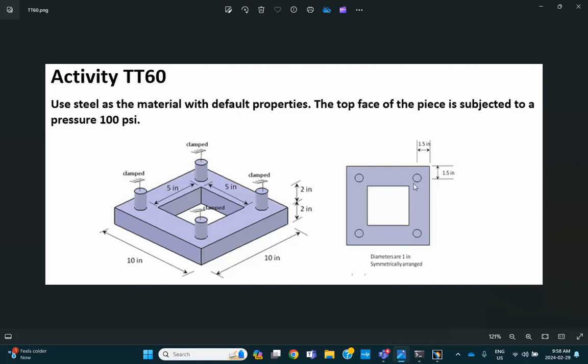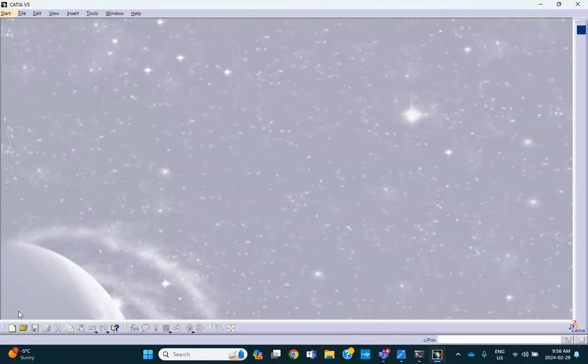Because notice that if you take a plane of symmetry which is vertically down, for example, and at 45 degrees in a slanted direction, what you get is a right triangle, which is repeated 8 times around this axis coming towards you. So basically, 1/8 of the model is all you need to do. After I do the problem without planar symmetry, I will come back and repeat that with planar symmetry taken into account.